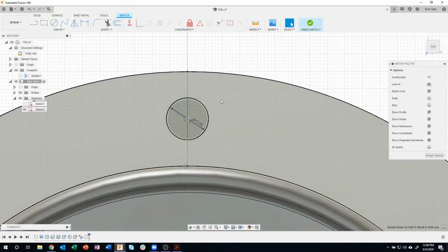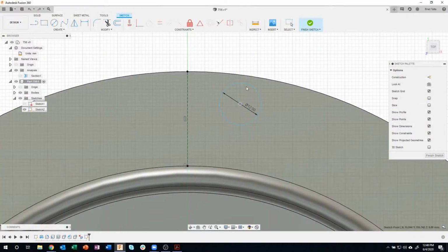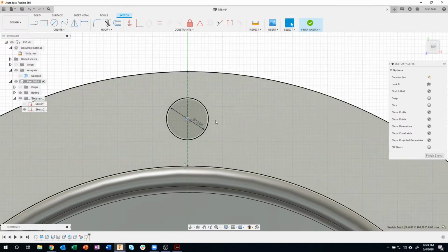There's two methods here. I can physically say, I want this to go from midpoint to this point here, and I'm actually clicking those two points. Or I can just drag what I want, and Fusion is going to try and build those constraints for me. Some people like to visually see, I say midpoint from here to here, and I even click way up here, knowing that, hey, it did snap to the midpoint. Or you can just, if you're comfortable with this, get it near and see it snap and drop, and then confirm that that is definitely the midpoint.